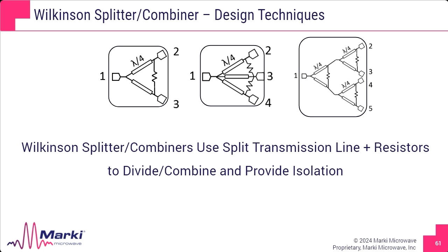They are designed to minimize the interference between these channels and also utilize the transmission line for splitting instead of resistors to avoid the ohmic loss. So we still have the 3 dB splitting loss, but now we only have transmission line losses on top of that. This makes for a significantly lower loss device than the resistive approach.